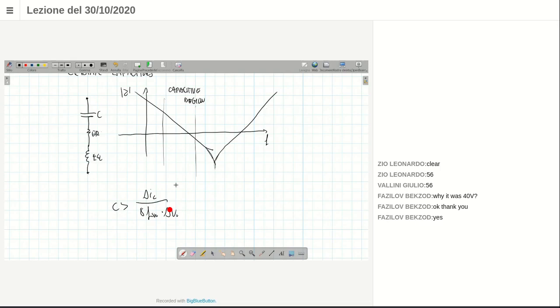I will not show you the derivation because I expect that you have seen this in class. Using the values in this example, 0.35 amps, 8 times 200 kilohertz times 50 millivolt, the required capacitance is 4.4 microfarad. That can be approximated to 4.7 microfarad in the E12 series.